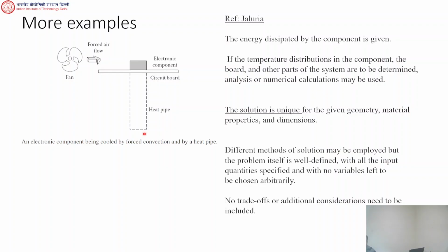The conceptual design can be just a fan, or just a heat pipe, or the conceptual design actually should be heat pipe plus fan, where typically you like to also use the fan around here to help the cooling. Whatever it is, that's a conceptual design. Then there are some calculations, etc. So that sort of thing we'll do later.